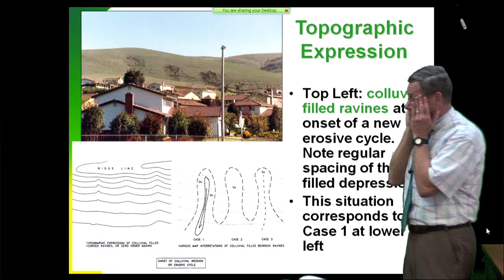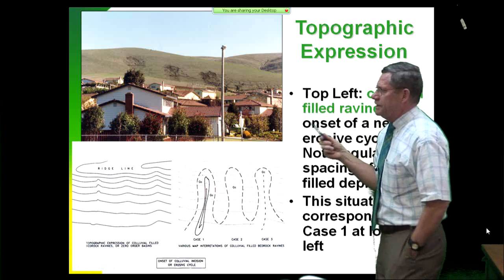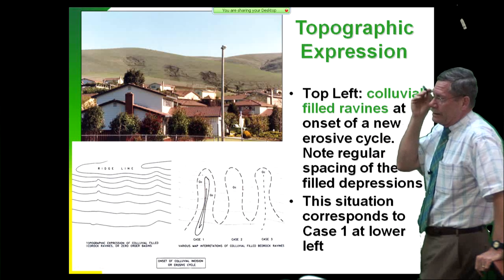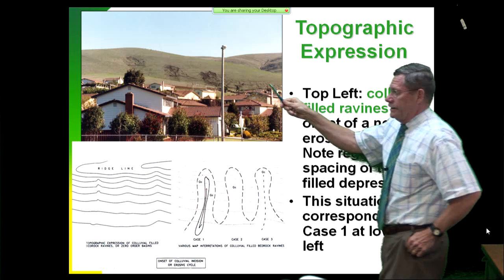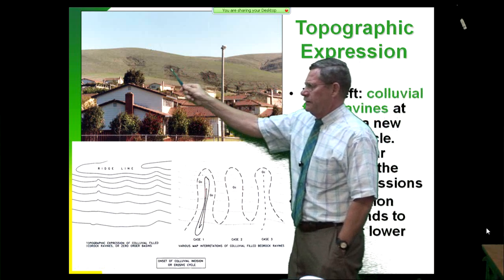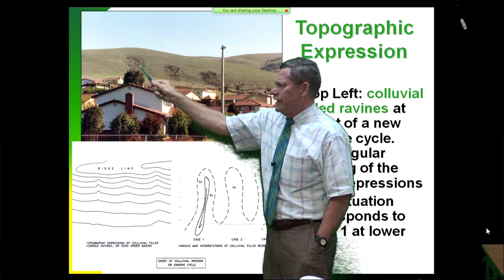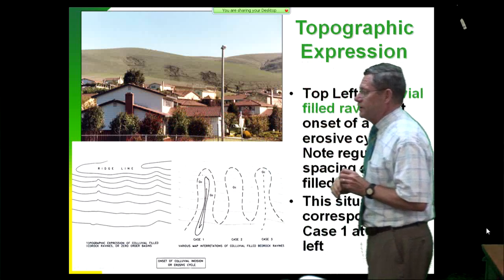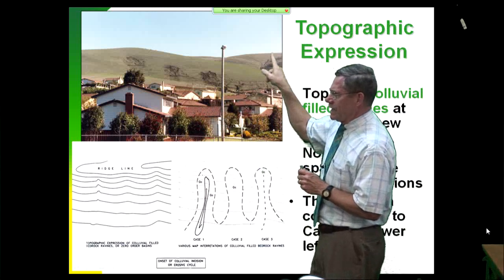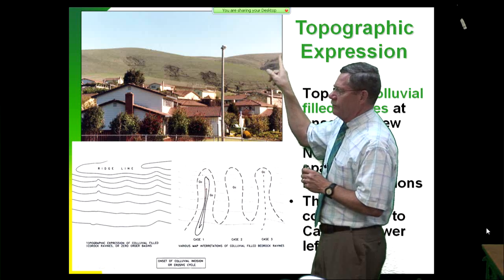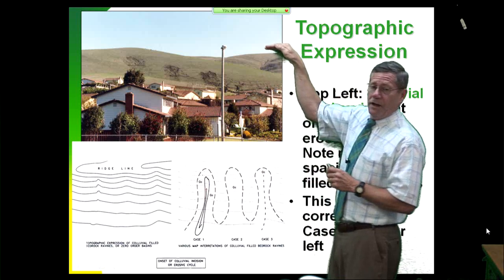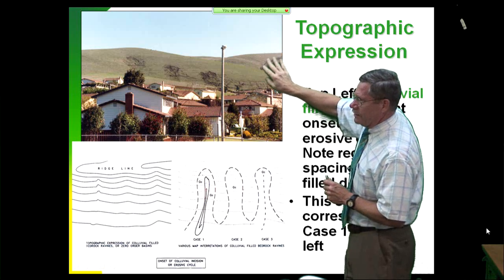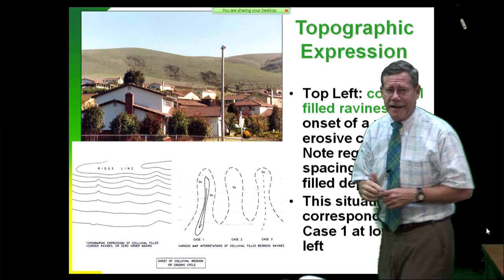This is one I had in the city of Vallejo, where they had a series of storms in 1986. They had a very heavy month in the middle of 86, and they had a series of failures that just suddenly lashed out and occurred right here, right above a brand new subdivision, scaring the people considerably, as you might expect. And then you look back up here in the higher hills, no problems. These are much higher, got more rainfall, but when you went up here and looked, these were bedrock ravines. All the colluvium had long ago been taken out of there.